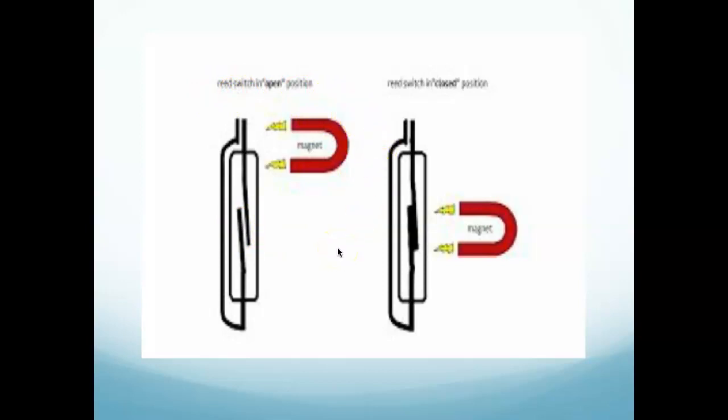A reed switch is really a common switch, and you wouldn't think about where you might use it, but think about, well, gosh, a lot of you have laptops. When you open the laptop, you notice how the screen lights up? It's a reed switch. When the old flip phones, when you opened your flip phone, it knew to open up and start up or to shut down when you close the flip phone, right? It was a reed switch inside. It's not a push button switch of any kind. You couldn't see the switch. You can't look and see a switch when you open the cover in your laptop. It's a reed switch. It's a magnet, and there's one in the top and one in the bottom, and when they separate, it sends a signal to your CPU to fire up and light up the screen and start your laptop. Same principle, easy stuff.